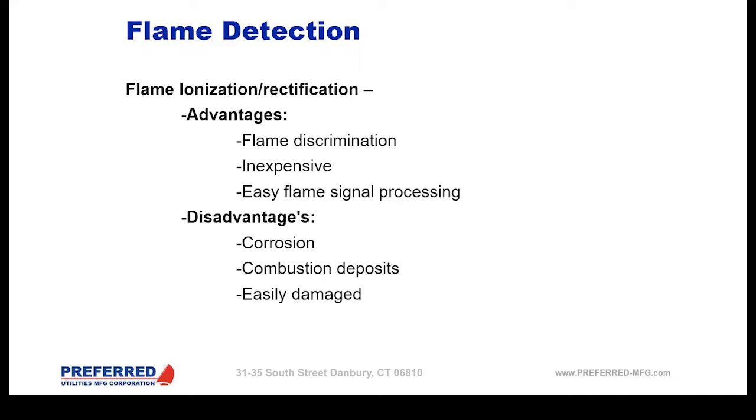So Steve, just to clarify, what the corrosion does is it builds up a layer on the flame rod that the ions can't pass through, so it acts like an insulator. And I've actually found that it's more of a problem on units that don't fire as much, more so than units that fire a lot. Because when the unit's down and it's condensing, that's when it gets wet and the flame rod will corrode. You're absolutely spot on.